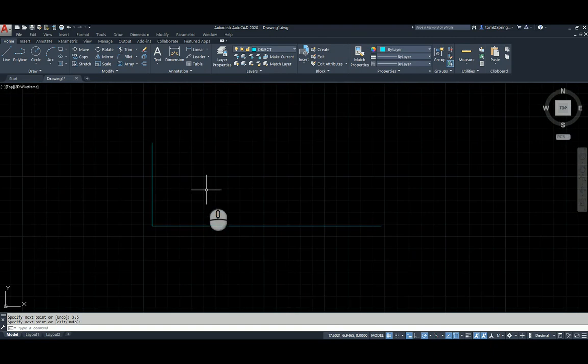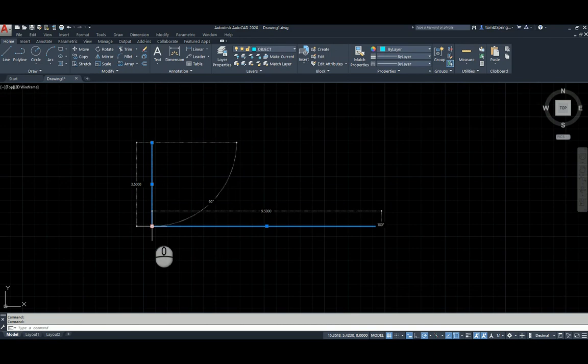All right, let's take a look at what we have. We have this right here. And if you ever want to check your geometry, you can click on the items, and if you hover your cursor over the intersection, you can actually get the dimensions. You'll notice that this grip, which is the square, becomes red. That actually gives us the distance right there, 9.5 by 3.5. We're looking good. So we're off to a good start.